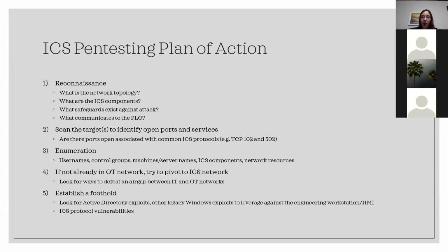Similar to logging software or taps used in an IT environment, there are similar things for an OT environment. So they can configure alarms, like if someone tries to write to a register or write to a coil, an alarm could be triggered, and then an operator would be immediately notified that, oh, hey, we may have an attacker in the system because someone just tried to write to this.